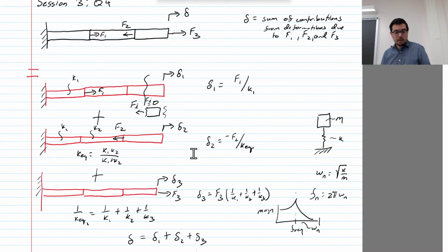All right, good. Since multiple people are working on it, hopefully that helps a little bit, and I can go around and provide further clarification. Yes, so to get the elongation, you pick D2 and subtract D. So to get the elongation of the middle member, we need to figure out what the internal force is.